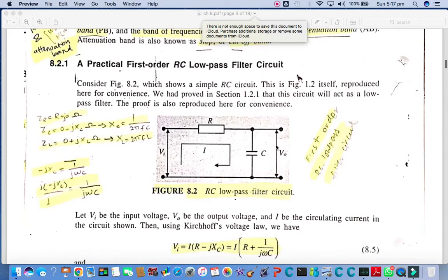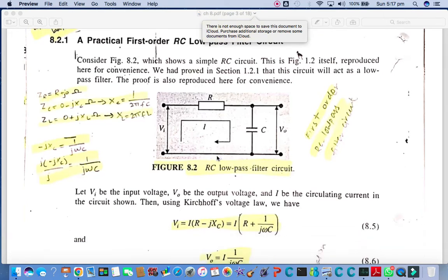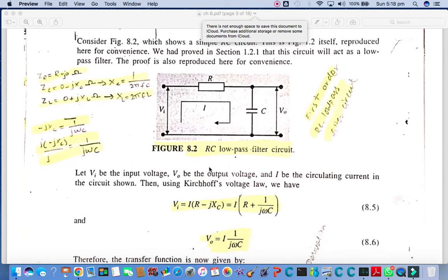Now we can see a circuit diagram of a low pass first order RC filter, and we are to derive the transfer function, or the impulse response, of that filter. The transfer function will be calculated with the help of output over input voltages. We have these two passive elements over here and we need to calculate their impedances. If there is a resistance, then its impedance will be like this. If there is a capacitor or an inductor, then their impedances will be derived from these expressions.